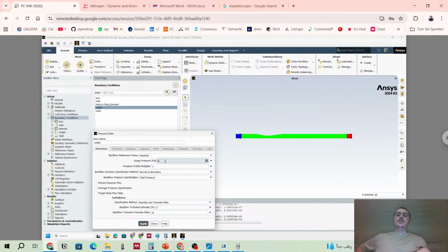After the software calculates the pressure inlet, we understand the pressure drop. If it gives you 1000, that means you have 1000 pressure drop. This is why we use reference pressure of 0 Pascal to directly understand pressure inlet related to pressure drop. So let's say, okay.